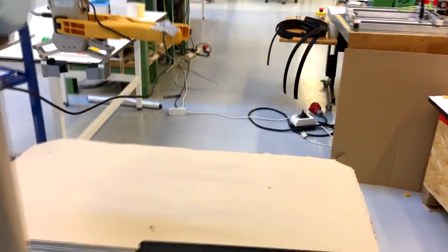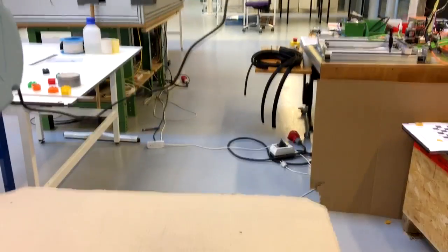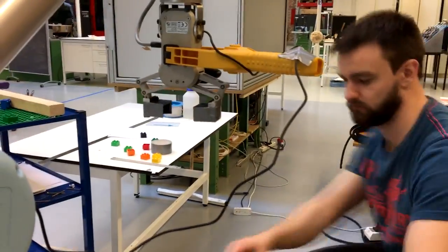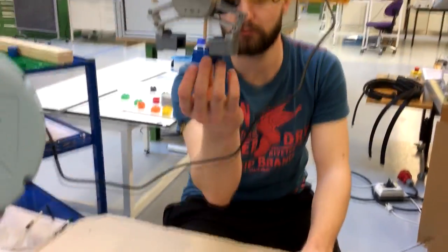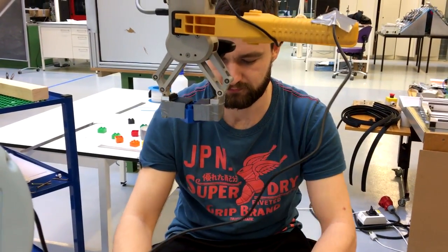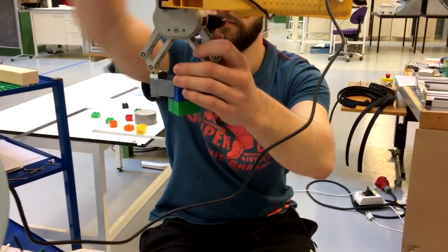And we initiate this combined calibration by starting the MATLAB script which connects to the robot, which will then initialize and go to a camera taking position, from where it will grab an image of the background to be used for the background subtraction. The next step is to place a brick in the hand of the robot, so we can calibrate the offset between the camera and the robot tool frame.